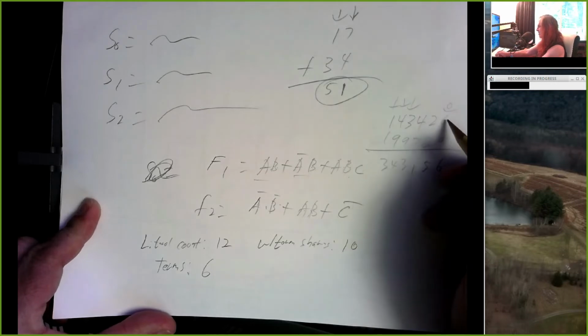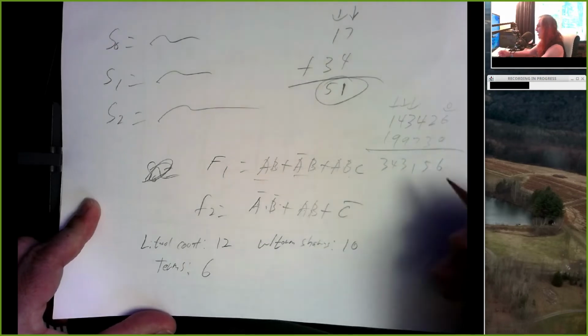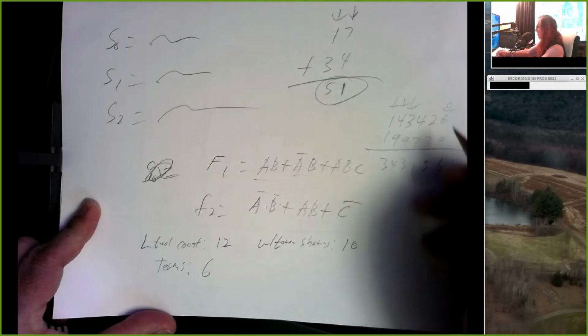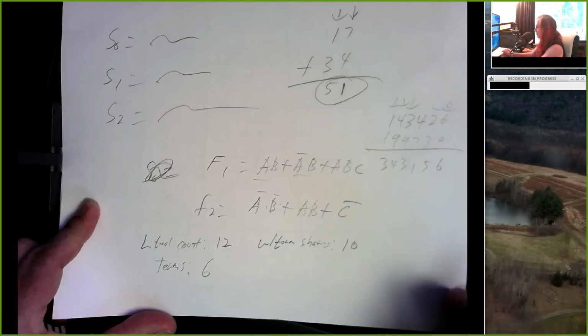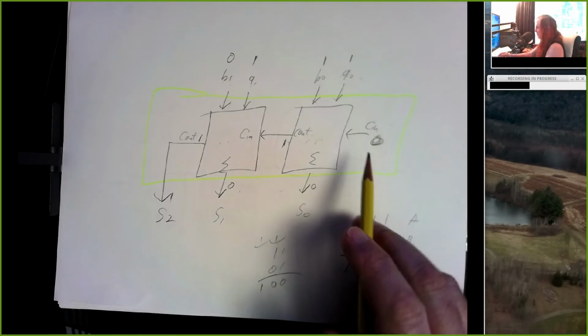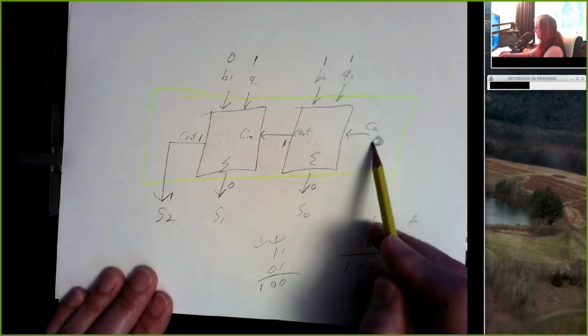We always start off with a carry of 0 when we add our rightmost bits or digits. And then if that overflows bigger than 9 for decimal or bigger than 1 for binary, then we get a carry into the next place and so on. But this very first carry in is always a 0.